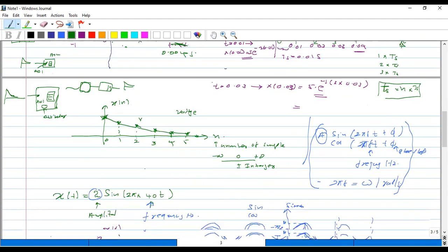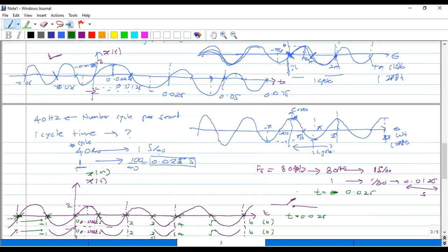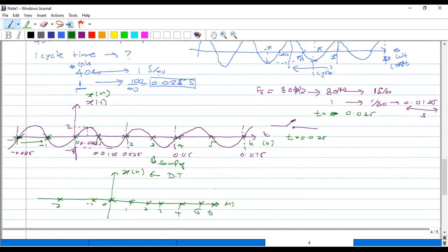But if you consider this signal, what happens? If you want to store this signal in the Arduino using this sampling, what happened? You get only 0 samples there. So in the memory locations you are storing only 0 voltage level. So after reconstruction, you will not get the signal. It will be a 0 value. In this case, you can't reconstruct this signal using these samples. That is a very important point, so you need to understand it very well.